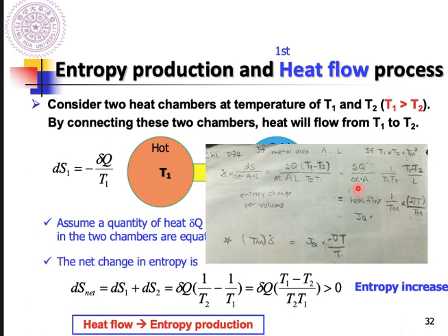And for the rest of them, I put a T1, T2 here. The driving force here is definitely related to the temperature gradient. So the rest of the terms are a gradient term, right? It's T1 minus T2 divided by L. Why is it a gradient? It's a delta T, a difference in temperature divided by the length, which we call a gradient term.